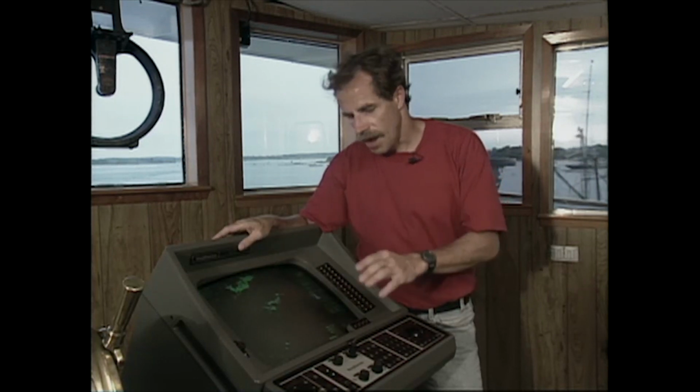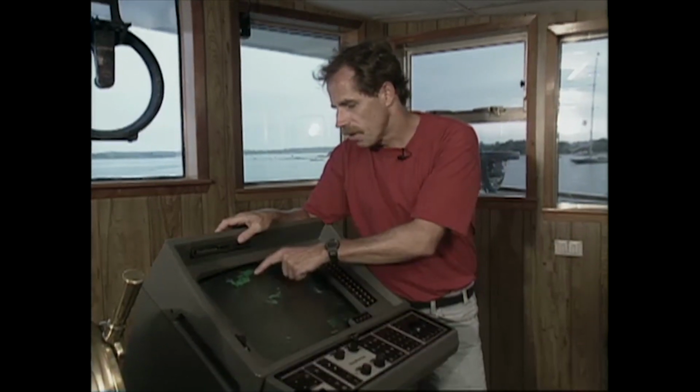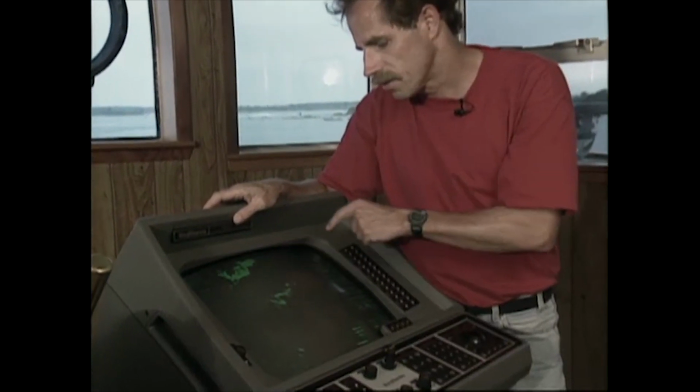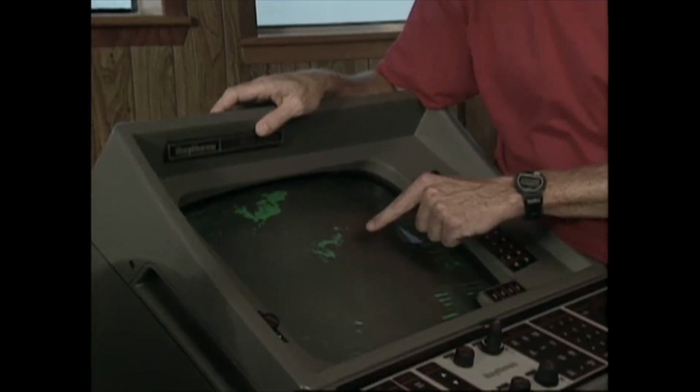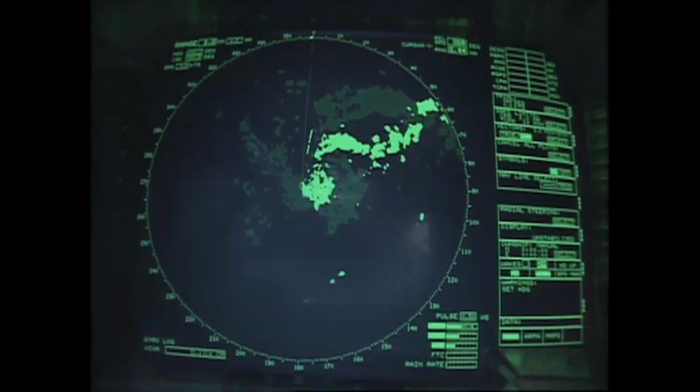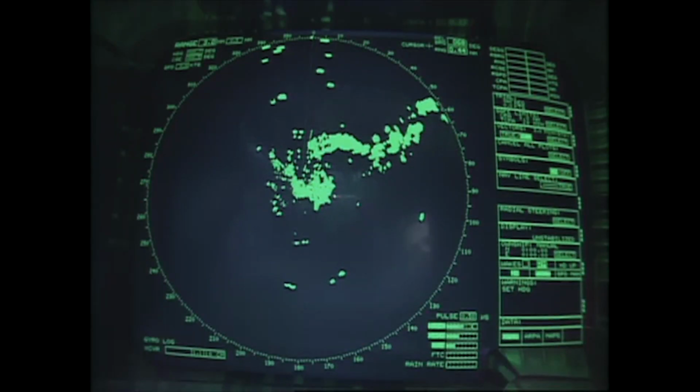We're now moored in Woods Hole, Massachusetts, heading south, and I've set the display up here at about a 6 nautical mile range. And you can see the coast of Martha's Vineyard across Vineyard Sound here. You can also see, if you look closely, in fact, let me increase the range, adjust the display a little bit. You can see the black area is the channel through Woods Hole. Now, as I said before, we also use the radar to avoid targets. The dots that you see in the black are actually individual ships or boats.